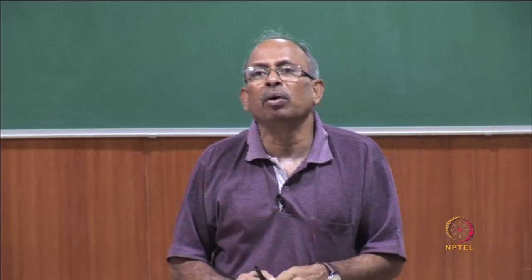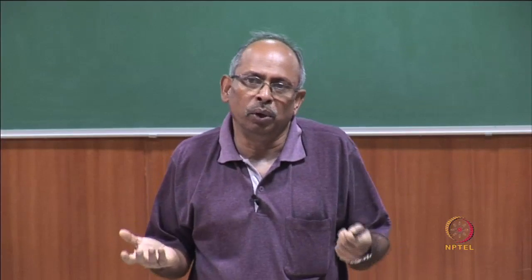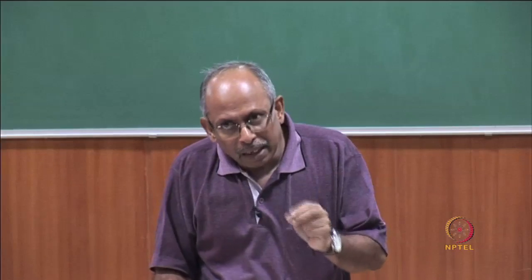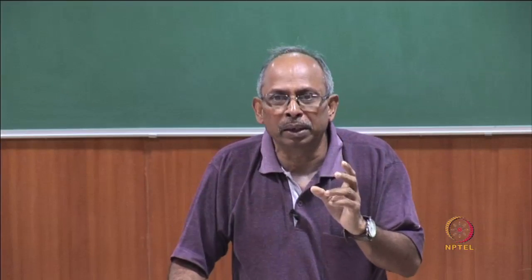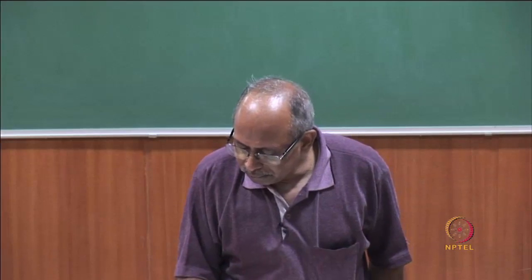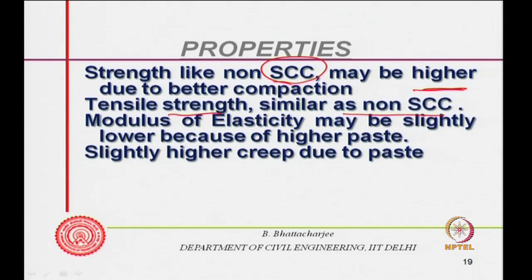Therefore, self compacting concrete will be as good or as bad as you design, maybe slightly higher, because of better compaction. There should not be any question on tensile strength. It will be similar to non self compacting concrete. After all, we have seen that empirically tensile strength is related to the compressive strength. So, therefore, there is no question.